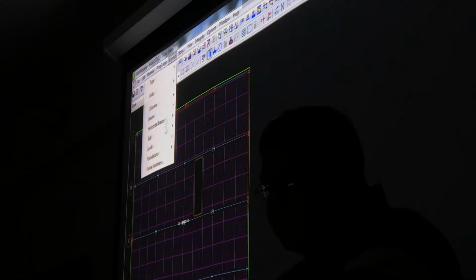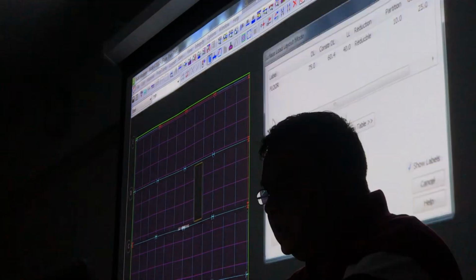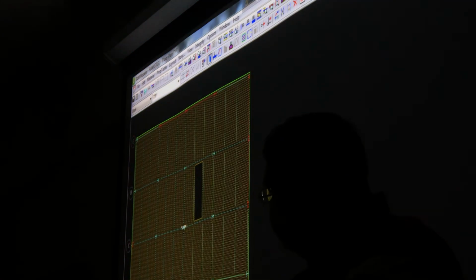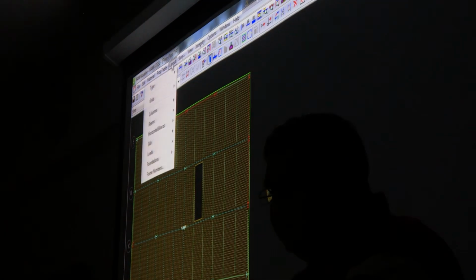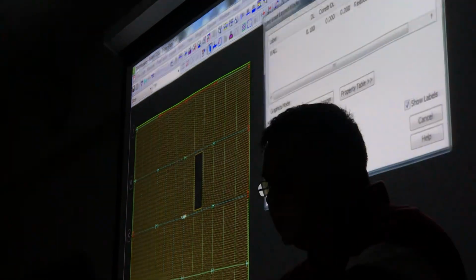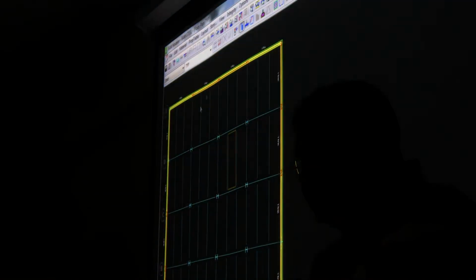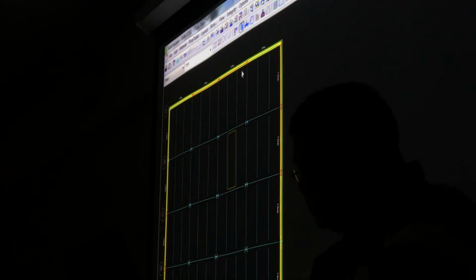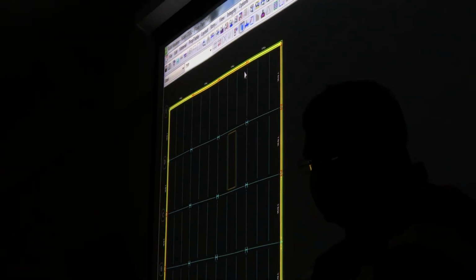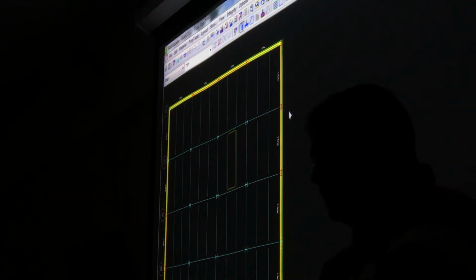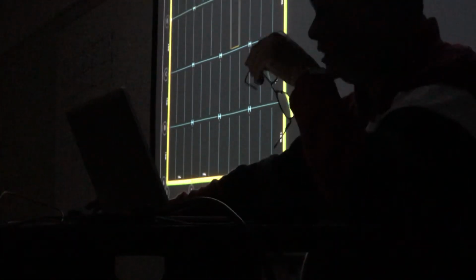Now let's apply the loads, surface load, and I'm going to say this is the floor load applied everywhere in the diaphragm. Live load, this perimeter wall load is applied at the whole perimeter. So that's my perimeter wall load. Okay, I am more or less done with the modeling of the typical floor.